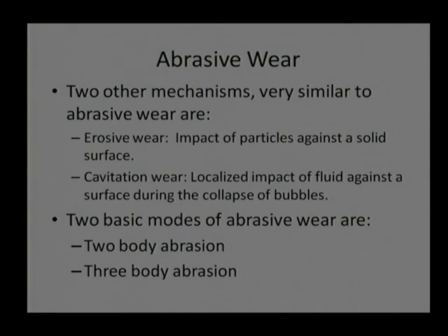This abrasive wear has a very common mechanism with erosive wear and cavitation wear. The only difference is that in abrasive wear we are talking about two solids, with particles not coming with impingement or impact, but with sliding or rolling motion. So, abrasive wear is generally solid versus solid, but particles are not coming with a high velocity, while in erosive wear we are talking about particles attacking the surface with a relatively high velocity. When we talk about cavitation, we are talking about the liquid which is making bubbles, or bubbles are induced because of one process or another, and they burst, releasing high pressure, and due to that pressure the surface is getting damaged.